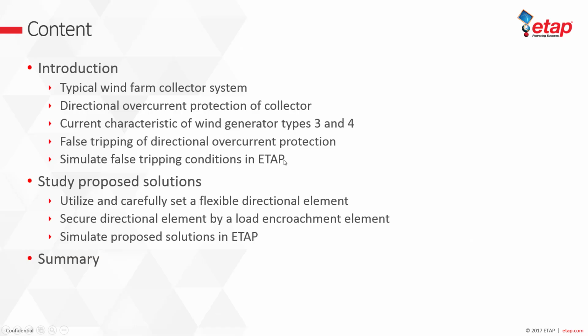In this webinar, I'm going to introduce a typical wind farm collector system and how directional overcurrent protection is applied for collector protection. We look at the current characteristics of wind generator types 3 and 4. We also go through the reports regarding the false tripping of directional overcurrent protection. We simulate those false tripping conditions in ETAP.